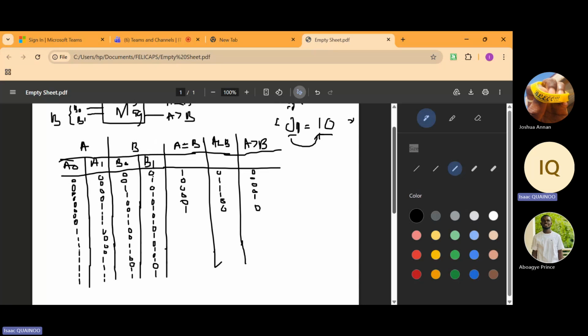And this is a shortcoming of magnitude comparators. One of the things that makes magnitude comparators difficult is that the more the inputs increase, the more complex your circuit and truth table become. So if you have anything beyond a 2-bit magnitude comparator, personally, I don't recommend doing all this in an examination.